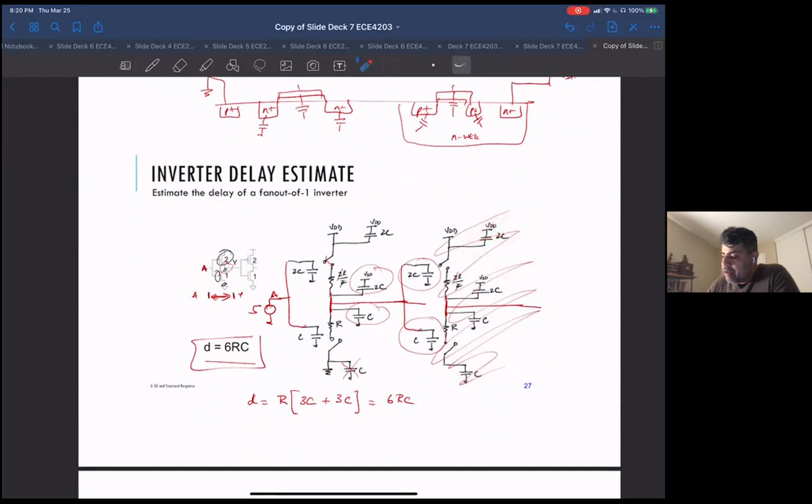And since we're being driven with a voltage source, we can ignore the gate as well. So we just worry about the middle part. And then we ignore the top, like VDD/2 C, and the bottom C. Exactly. Because note that this capacitor, both top and bottom, are connected to the same DC voltage, so it's not adding any delay or any transitions. It's not changing at all.